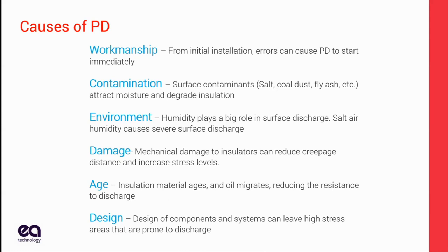Age. Some materials, not so much the solid state materials like XLPE, they don't age too much, but PILC, the oil can migrate away from certain high spots in a cable, leading to PD. And then design. Doesn't happen very often, but you'll get components that are not designed well, or they're designed such that they're so hard to install that they're never installed correctly. That's kind of halfway between workmanship and design. But if it's too hard to install, then you shouldn't be using it. So these all contribute to cause PD in the field.